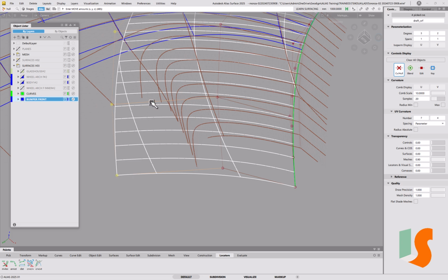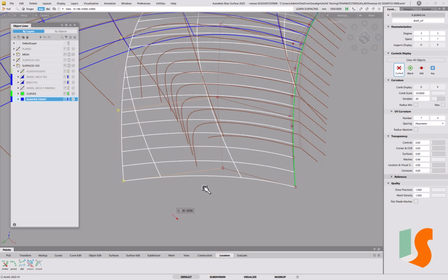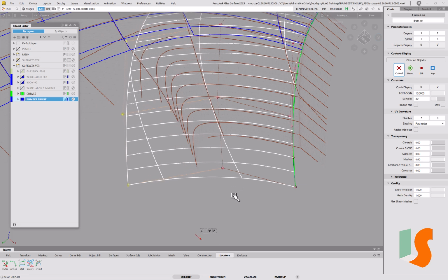So what we want to do with the spacing of the CVs, currently this is quite uneven, we've got those two close together and that one is further apart, and so we want to push this one much closer in, because that's the acceleration of curvature that we want, which is actually flat to tight. So really the spacing should be, this is quite big and then the next one should be quite small. So I'm going to move this whole hull here back in the X direction now. So in side view we're going to keep a nice shape there.